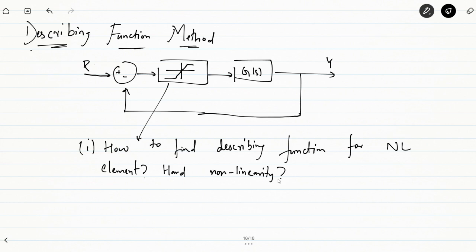So here the describing function method is much more useful for nonlinear systems. We can get a complete equation of the system. We can check how the hard nonlinearity is behaving in the system and analyze different properties. Once we have the describing function, we can analyze the stability of the nonlinear system by extending criteria for linear systems such as the Nyquist criterion or Routh's criterion.